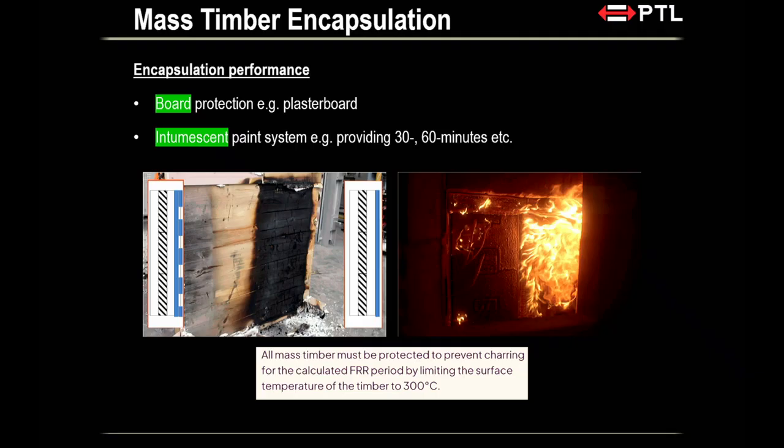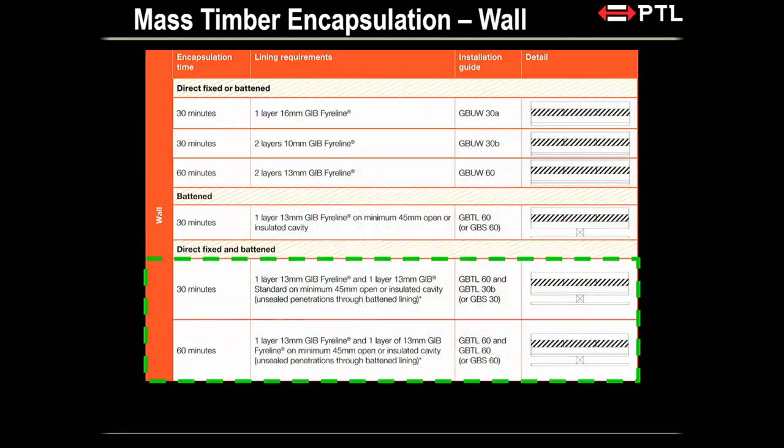White, yeah, that's the thing. A lot of clear intumescent coating is to provide surface finish protection to achieve a group number, that sort of thing. They are clear for a reason, because the architect still wanted to see the timber. Encapsulation is painted in white paint, otherwise it's still there anyway.